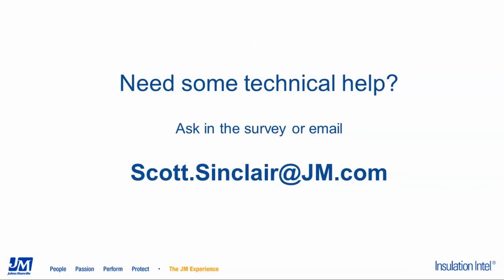That being said, it really depends on how often you're going to see water intrusion. You really hope that your system doesn't see repetitive water intrusion, wet-dry cycling within your piping system. So I would like to say that I can give you a number of years, but it really depends on that whole system and how well you can maintain the integrity of your system as a whole. The better you maintain your system, the longer it's going to last. Obviously, as we saw, if it's getting 40 plus wet-dry cycles, you are going to lose some effectiveness. That being said, it's never going to actually fully leave the insulation system.